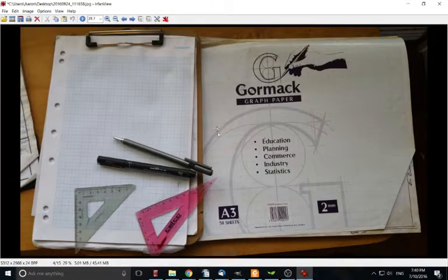Okay, so I just got something up there where it was. So what I usually take out to a job site is some graph paper with 1mm squares, and this is an A4 sheet on the left. And what I'm typically drawing is 1mm equals 100mm. That's my scale, so 1 to 100. If it comes out to millimeters or halfway, well, good enough is close enough in this sense. It's going to get us pretty close to what we want.